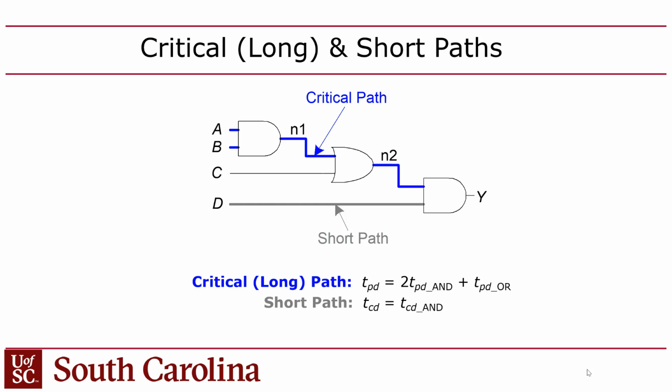But the caveat there is that we don't run it anywhere near that high of a temperature. So the FPGA tools will tell you what the delay is, and it's kind of a pessimistic number. I have done this quite a bit myself, where I overclock. You can overclock your FPGA circuit. You can run a little faster than what the tools tell you, because it's determining those delays as kind of worst case delays.